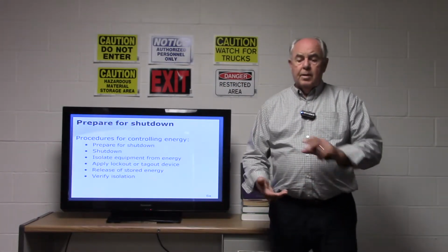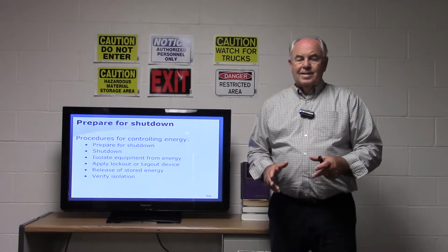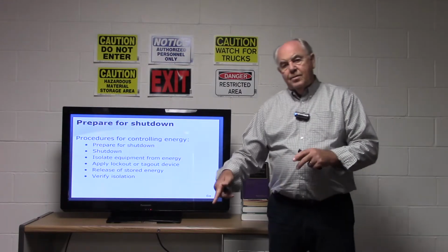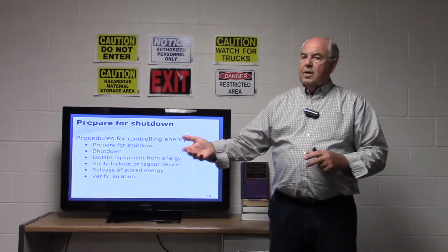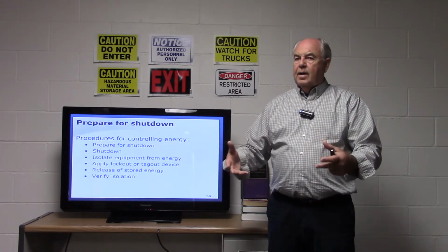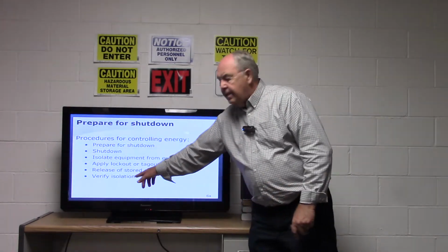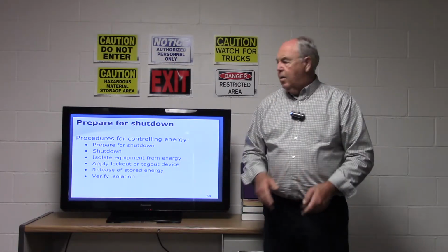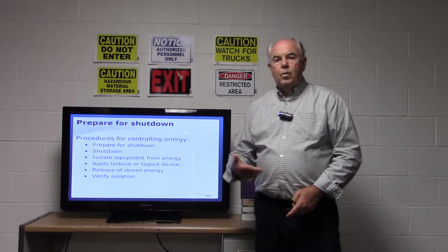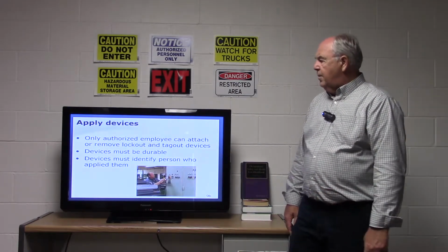Once you hit the start button and it moves, you may have just discharged the capacitor. So hit the start button again. If it moves again, then there's another source of energy coming in that you need to track down and find out where it's coming from. If it doesn't move the second time you hit the button, then you're probably ready to go at that point and proceed on with maintenance, repair, service, whatever it might be.